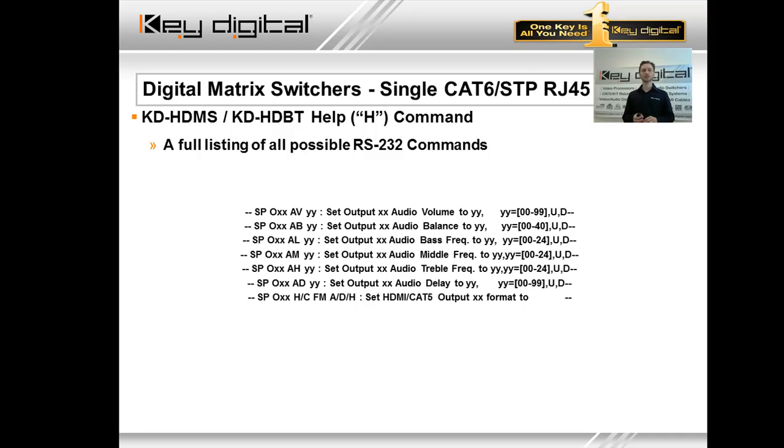That is because of a color spacing issue. And HDMI and DVI, for the most part, again, should be compatible, but sometimes you do have a color spacing issue. Only Key Digital, for my money, allows you to determine and force. Out of the box, it's on auto. The matrix reads the display that's connected and asks, are you an HDMI connection or a DVI connection? And it will accommodate appropriately. But sometimes that's not enough.